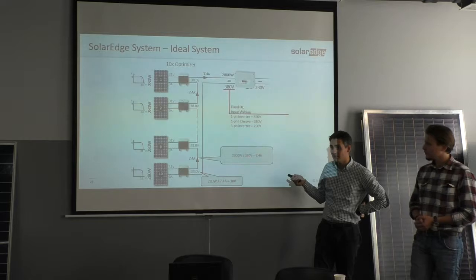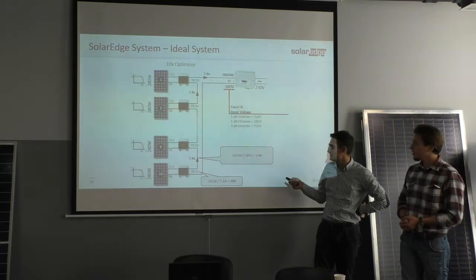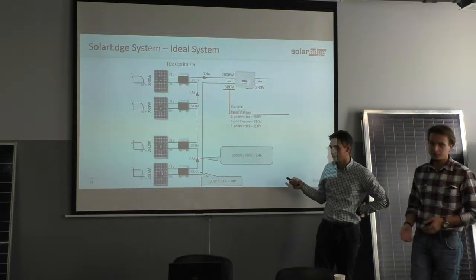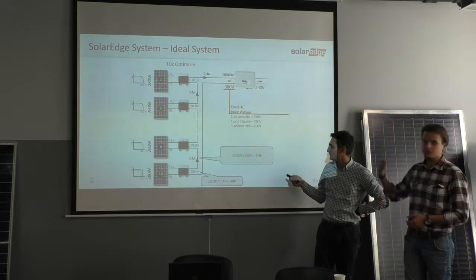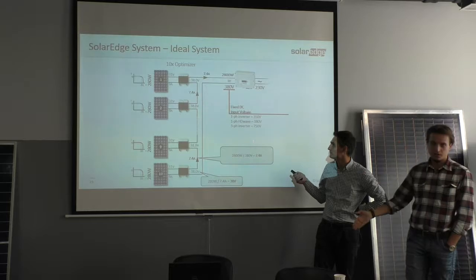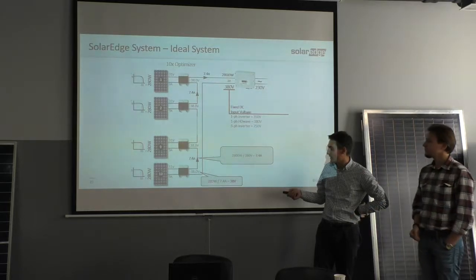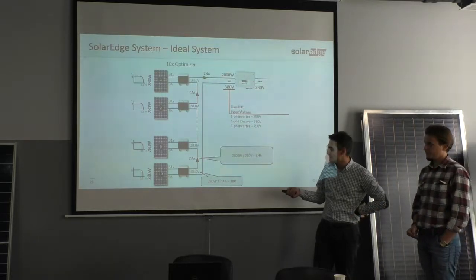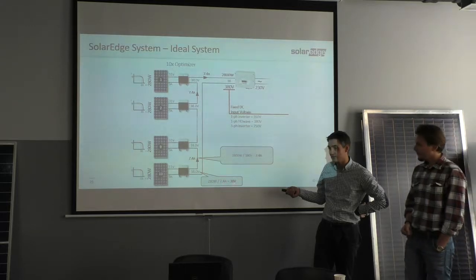Divided by 380 fixed voltage of the one phase inverter. Разделяем мы на фиксированный вольтаж однофазового инвертора 380. We have 7.4 amps. Получается у нас 7,4 ампера. And to check it, 280, the power of the optimizers, divided by 7.4 gives us 38.